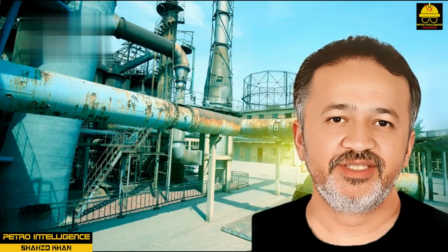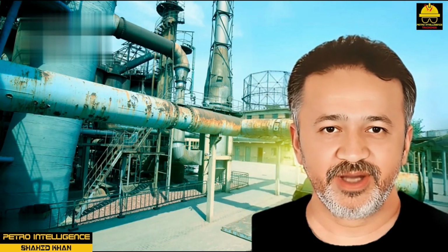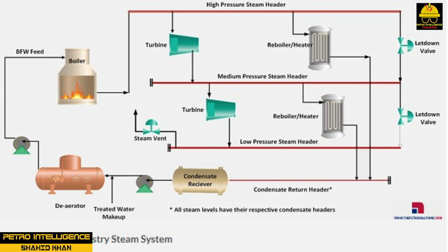Medium pressure steam system, 180 to 200 psi. Nominal steam pressure in the MP steam header is 180 psi. Medium pressure steam is supplied by lowering the pressure from the high pressure header or by extracting exhaust steam from steam turbine operations. As high pressure steam enters a turbine, it is partially converted to useful mechanical energy.